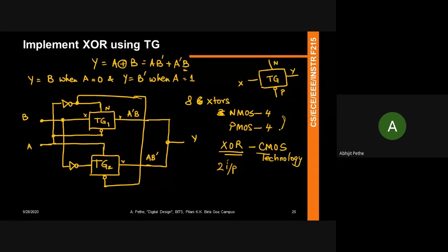Ramnathan, how do we intuitively describe the high impedance state? Intuitively, if you think about when we discussed digital logic families, right? Whenever you see a 0 or a 1, it is associated with certain current flowing into or out of the gate, right? Whereas high impedance is something where there is no current flowing. The circuit is designed in such a way that the output cannot supply or sink a current. So it is kind of a third state where that output is hanging, if you will, right? It's not a 0 or a 1. It's a manifestation of the current and voltage at that particular node.